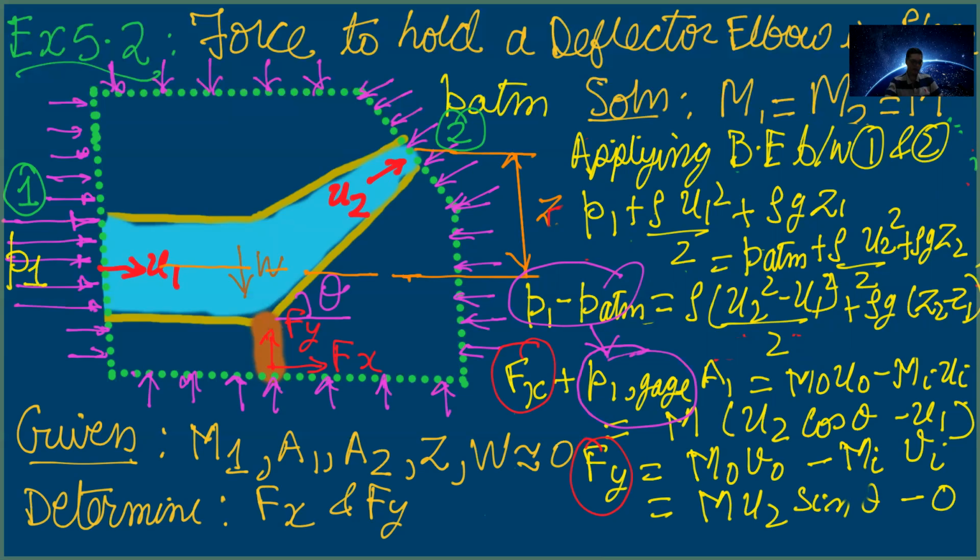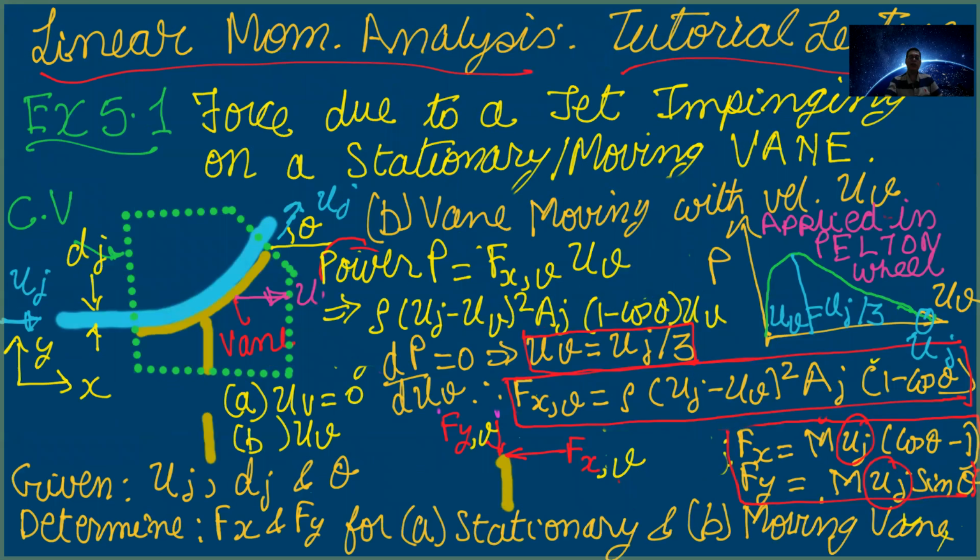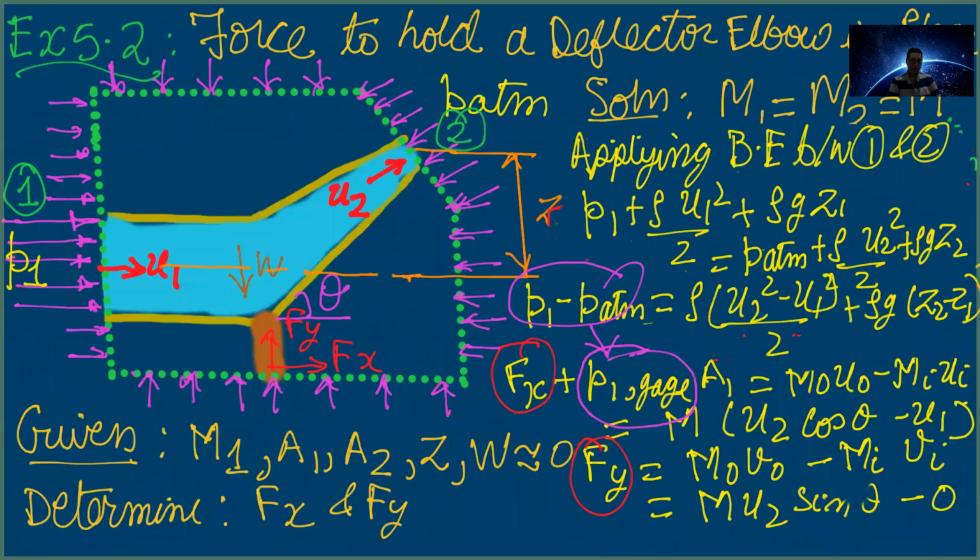which is as shown here, this problem is an external flow problem. Okay, here the jet is under atmospheric condition and the jet velocities at the inlet and outlet both are, because every jet is in the atmosphere, so its pressure is uniform everywhere, it is atmospheric. But the second problem is an internal flow problem where it is flowing inside a deflector. However, it so turns out this water is exiting at the atmosphere, so that's why you have an atmospheric pressure at the outlet.